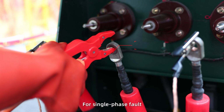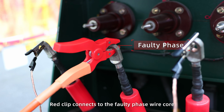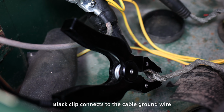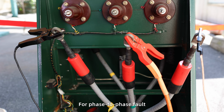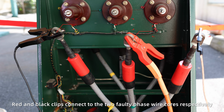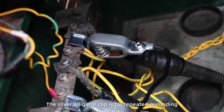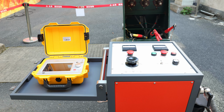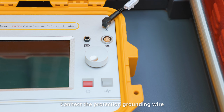For single-phase fault, the red clip connects to the faulty phase wire core. The black clip connects to the cable ground wire. For phase-to-phase fault, red and black clips connect to the 2 faulty phase wire cores respectively. The silver alligator clip is for repeated grounding. Connect to system ground. Connect the protection grounding wire.